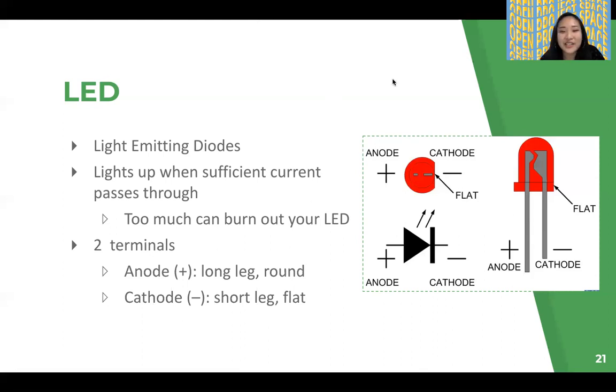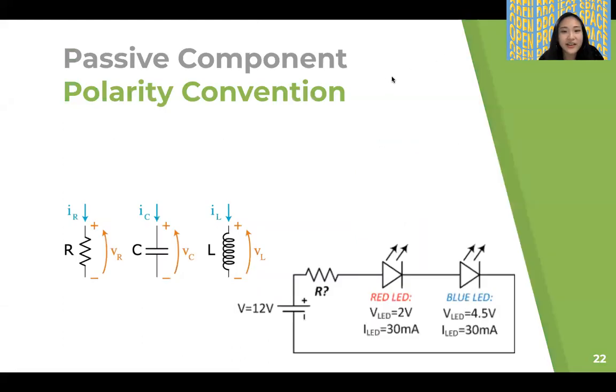And yes, very good question. If you see here, this is what we have for our sign convention. When looking at the circuits, we have to understand which way the current's flowing through the circuits. We usually assume a way the current's going, and in a simple circuit like this, we assume that the current's flowing out of the positive end of the battery.